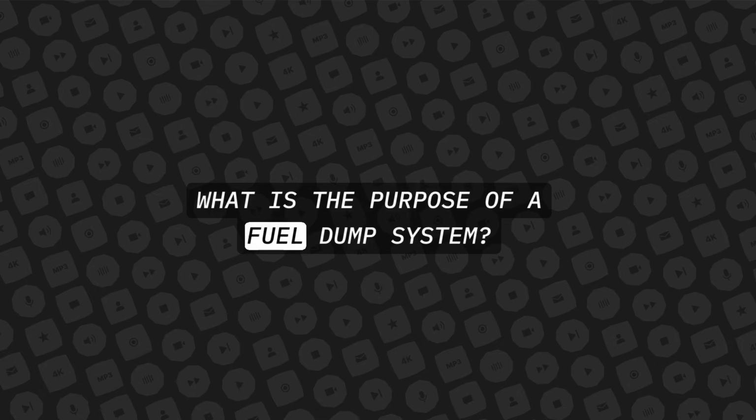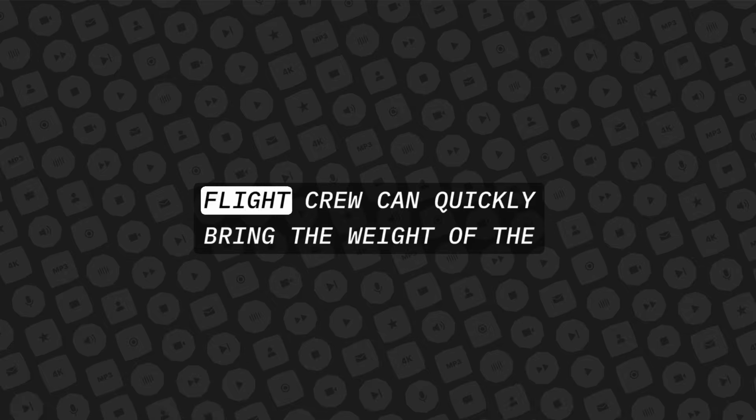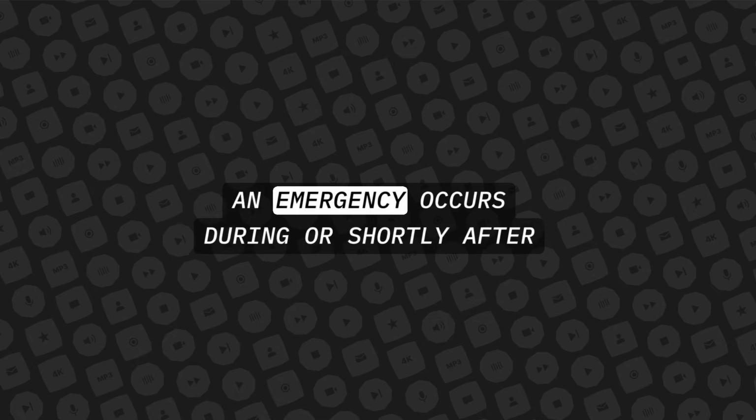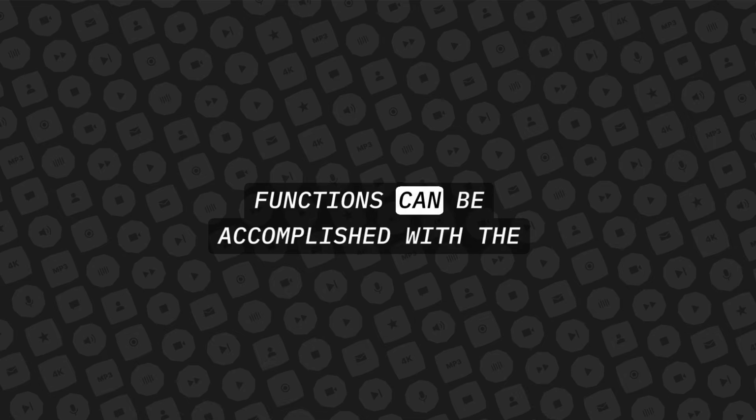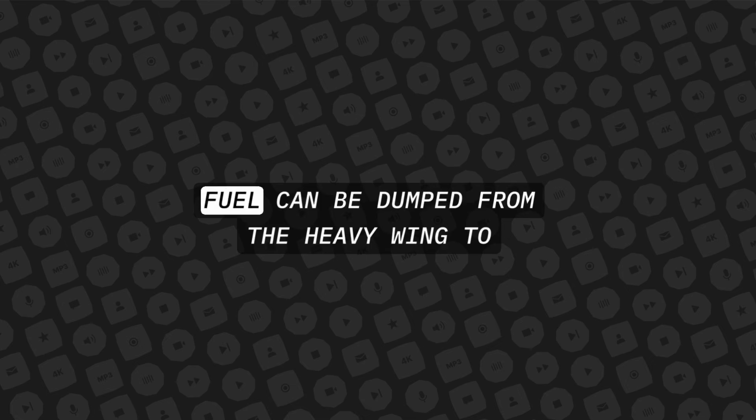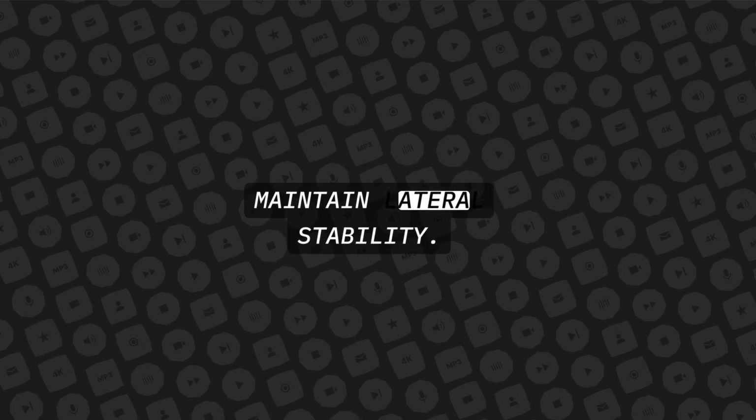What is the purpose of a fuel dump system? It is an emergency system provided so that the flight crew can quickly bring the weight of the airplane down to the maximum landing weight if an emergency occurs during or shortly after takeoff. Other than reducing weight, what other functions can be accomplished with the fuel jettisoning system? Fuel can be dumped from the heavy wing to maintain lateral stability.